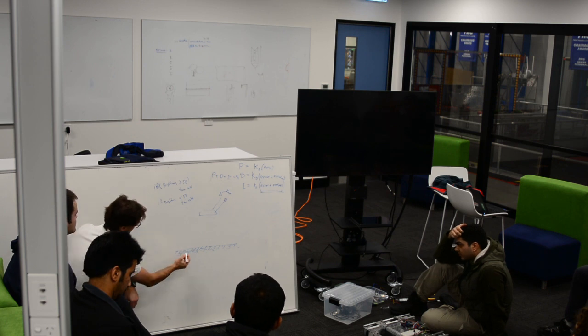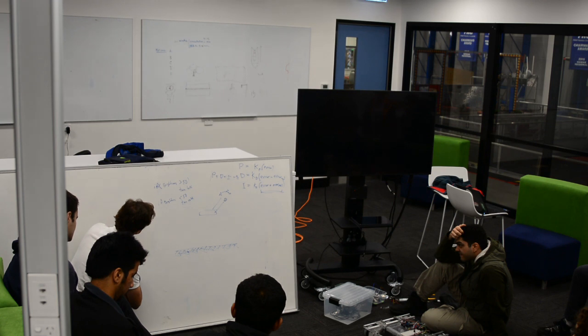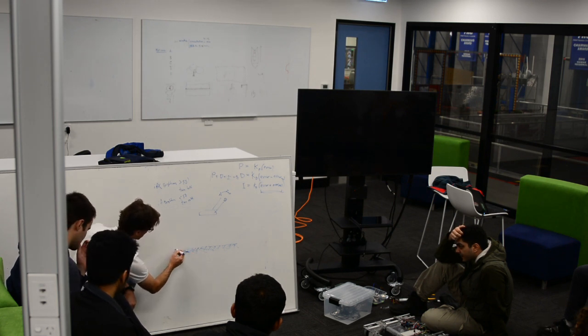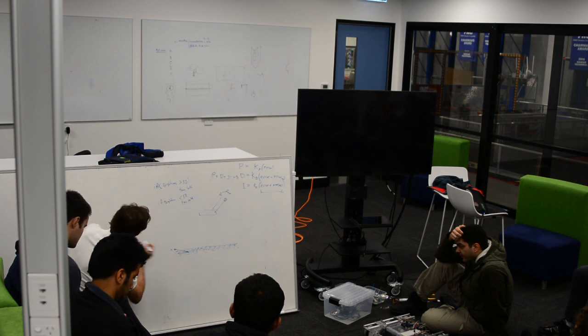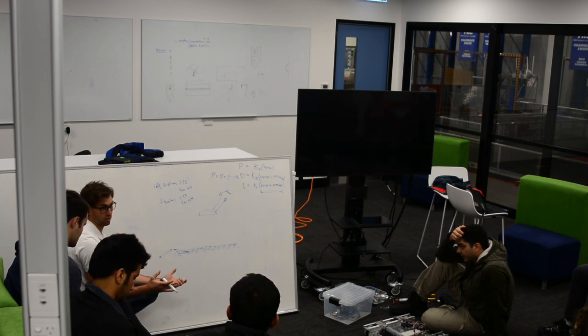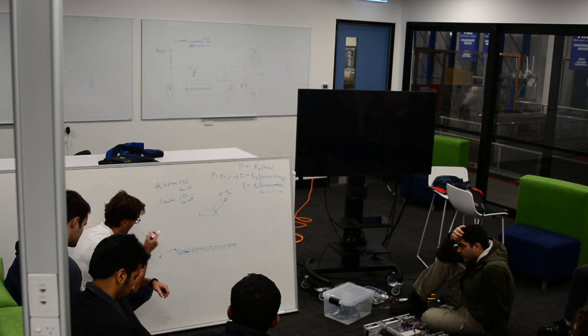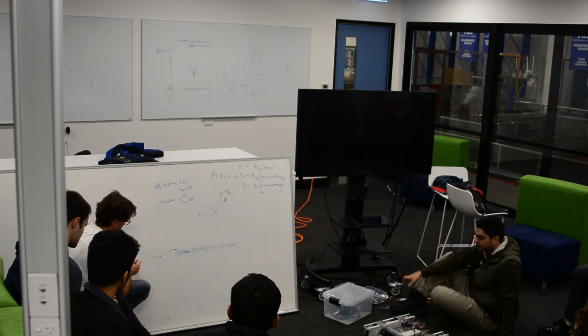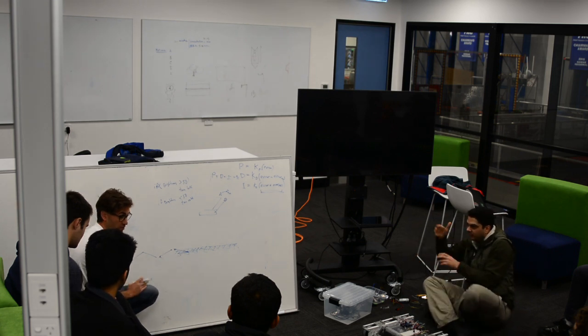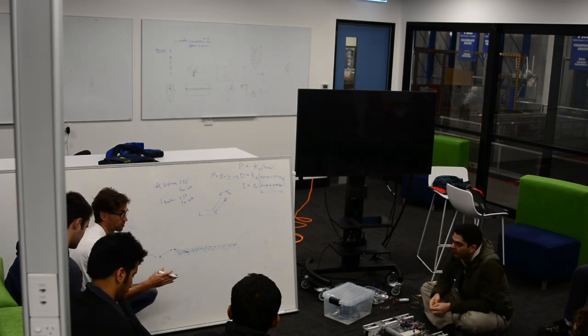The robot, if it's here, is going to turn to the right. So let's say that it's moving this direction. It'll go this way. If it's in the bright spot, greater than 50, it's going to turn left and go this way. If you try to go that way, it doesn't work, right? It runs away. So this thing is going to sort of go like this down the line. It doesn't go straight, it always zigzags. All line followers will zigzag. They're like little sewing machines.